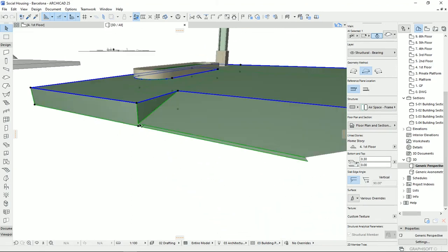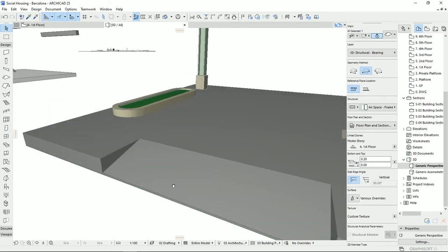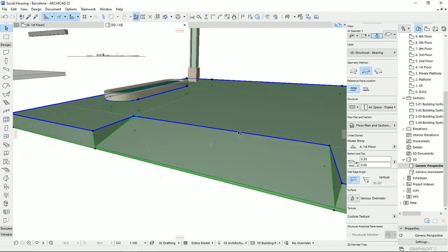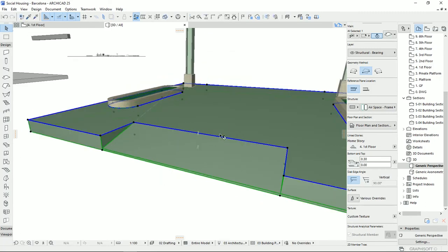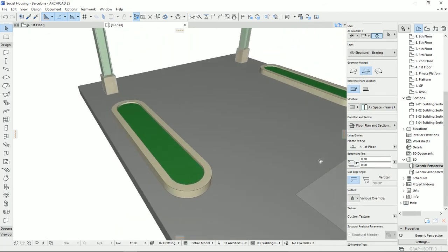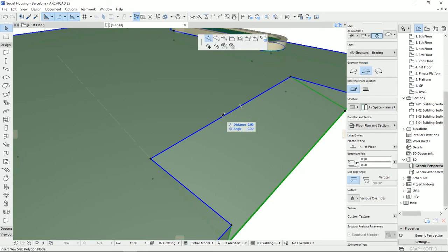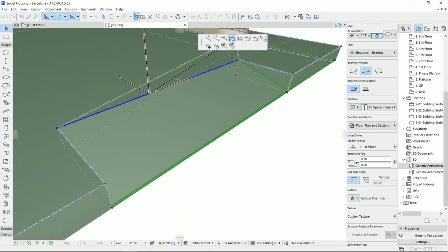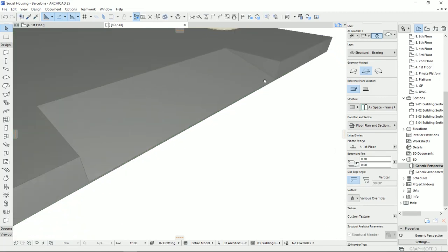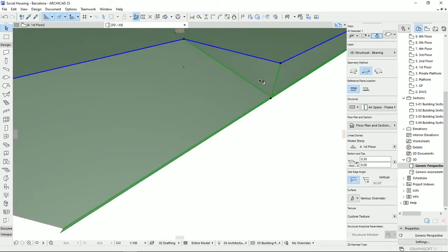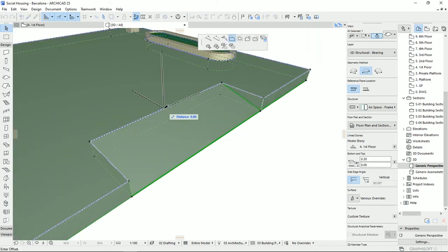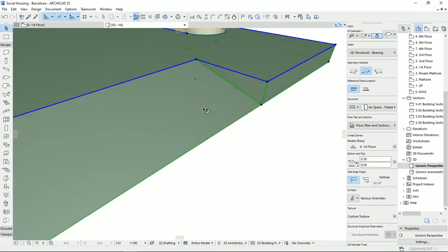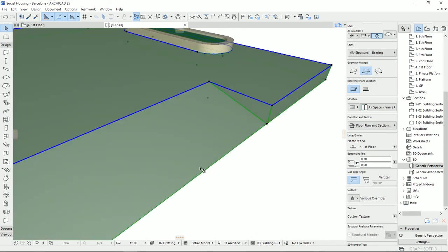Also, you can work a little bit more on these angles to have no thickness for this part. Also, if you want to have a specific angle for this slope, you can use the offset edge to move this edge a little bit back. I'm going to do it right now. I'm going to select the edge and hit the offset edge, and I'm going to move back a little bit like that. Now it looks better. We don't have any more thickness. Also, we can do it a tad more, like that. And then it seems that we have a very neat cutting here.